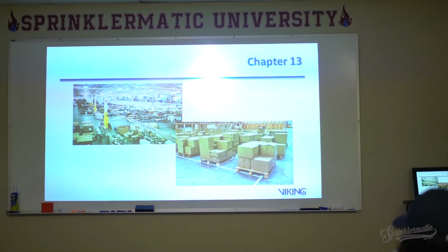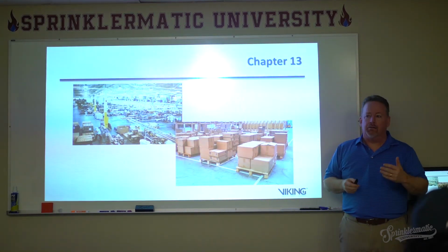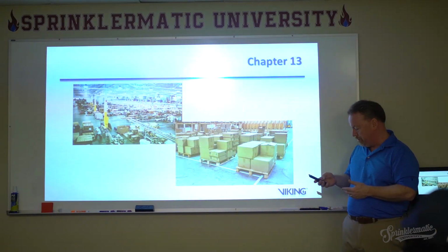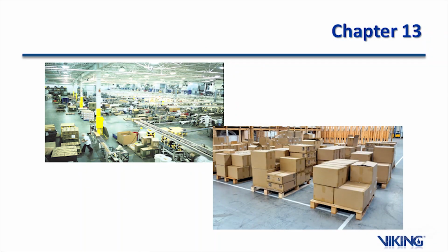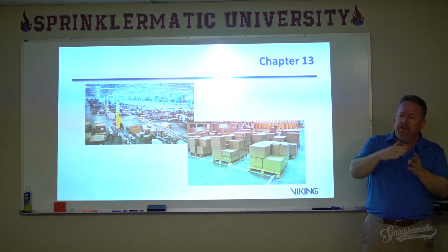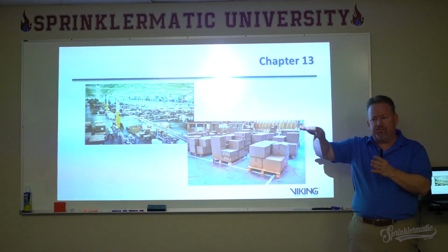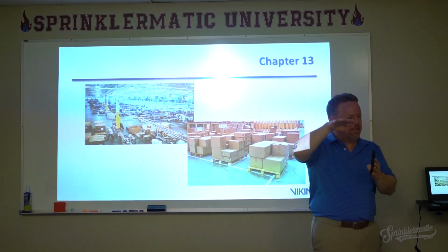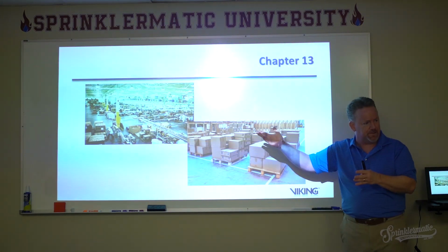All right, so after Chapter 12, you come to Chapter 13, which deals with what we call miscellaneous or low pile storage. So in NFPA 13, you have the occupancy hazard classifications: light hazard, ordinary hazard group 1, ordinary hazard group 2. They all stop in their storage height at 12 feet. So at 12 feet, that's kind of the end of occupancy class. If you have storage above that, you have to go to the storage occupancies.